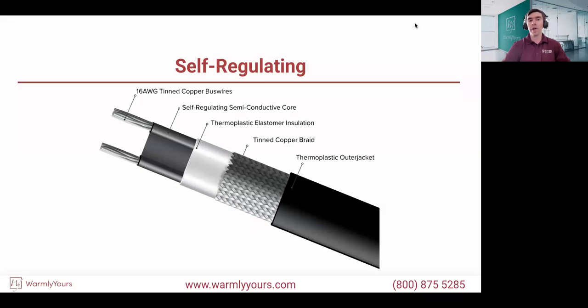The core is where the heat is generated. The self-regulating cable, the whole nature of that cable, is different than any other heating cables or systems, right? If you're familiar with floor heating or slab heating or snow melting, you know that the actual heating elements are those main wires. This is not the case here. Those are not heating wires or heating cables or elements.